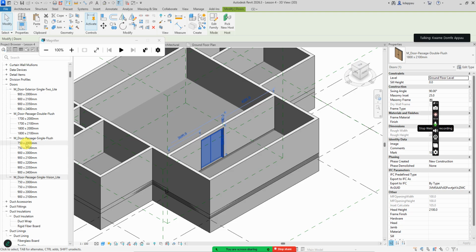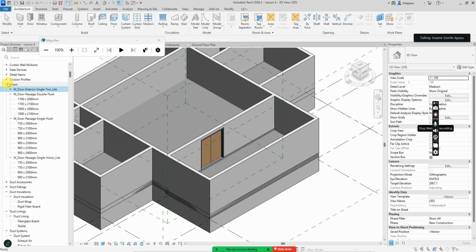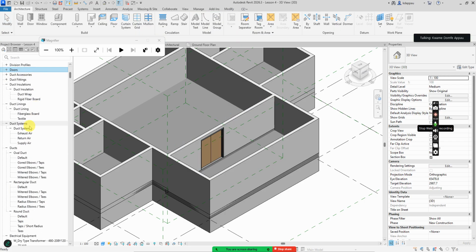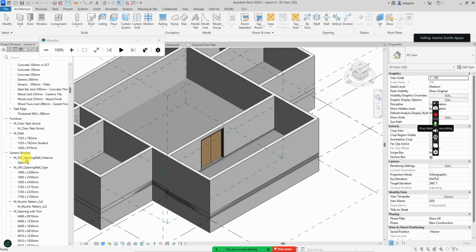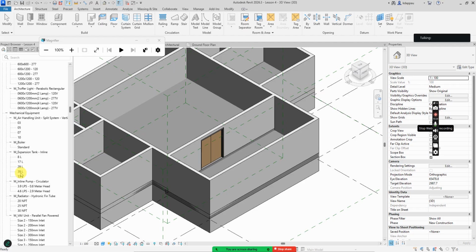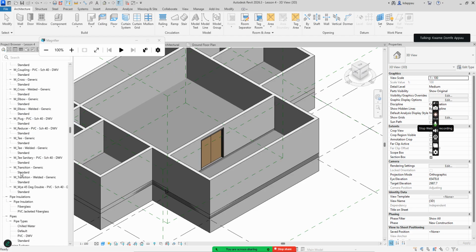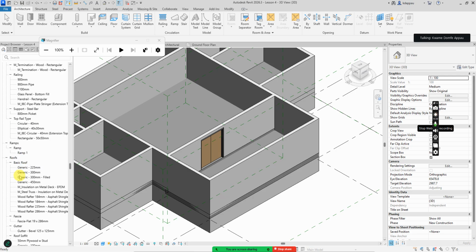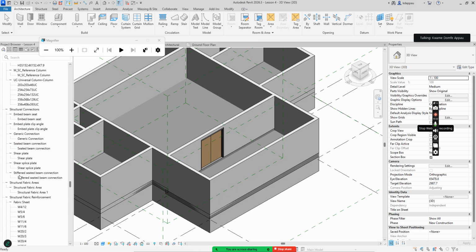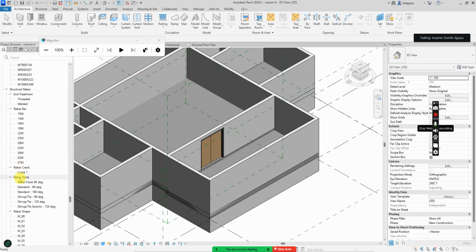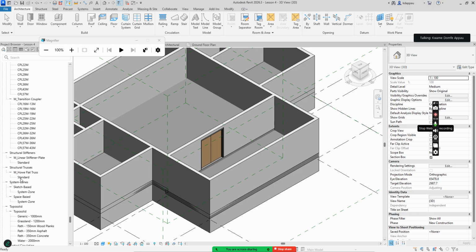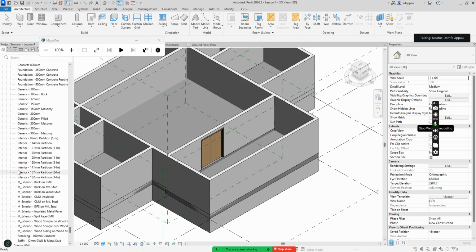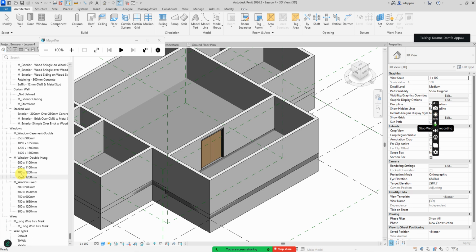So later on, we are going to delete those doors, or purge them from the project. Let me check windows also. I'll scroll down to where windows are, and then check how many windows are in the project. It's in alphabetical order. The list is very long. The thing's loaded, so I'll scroll all the way down. See walls. Then I'll come to windows.